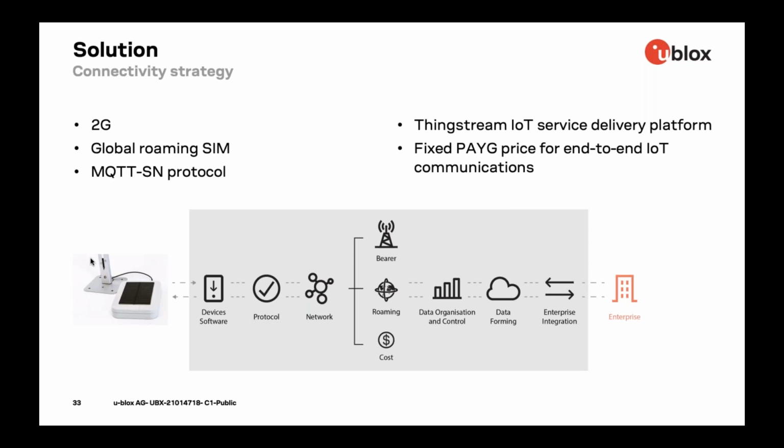So again, a similar kind of story to what you've seen before. We're not advocating 2G as the solution going forward. It's great for now for certain use cases, and we clearly recognise LTE-M is moving to be the next roaming low power capable cellular offering. NB-IoT we see as being excellent, and we see that more being used in domestic or municipal applications. So when considering IoT and your connectivity options, the point we're trying to make is think about the biggest market your customer could sell to, and how to pick the right connectivity and additional components to make this a cost-effective implementation.